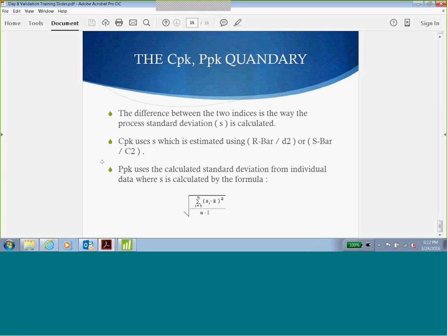As I mentioned, Cpk has only a few variations, from just one production equipment in this case, for a short period of time. Whereas with Ppk, you are including more variation and a more accurate estimate. You will know how well your manufacturing processes or manufacturing operations run.